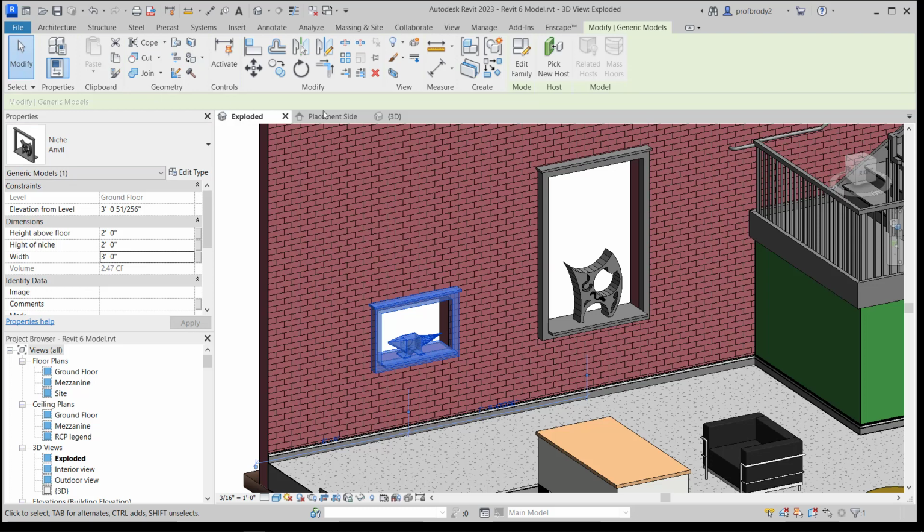There are many things that I did not create here. I probably should create some kind of back to this. I could insert lighting components inside this and have those turn on and off as you edit the component. And these are things that you will see as you travel through the world of BIM objects, not 3D Warehouse, but Revit City. You'll find all sorts of families, and they are created many different ways. So trying sometimes to modify the dimensions. For example, I was able to modify the width and height here as instance parameters because that's kind of the random way I created it.